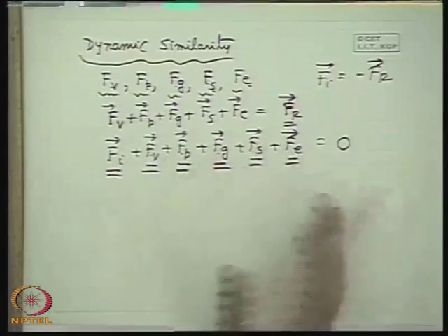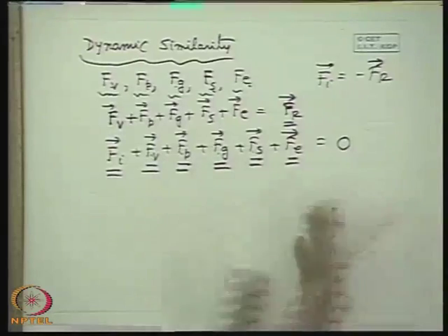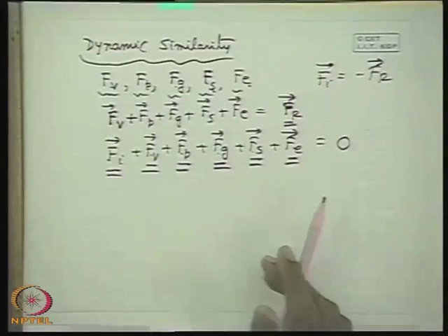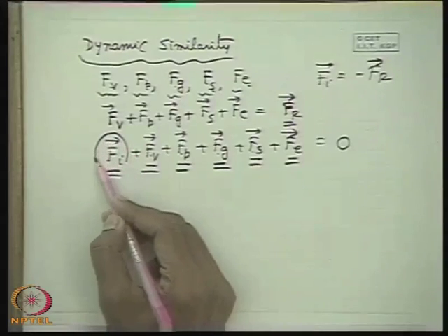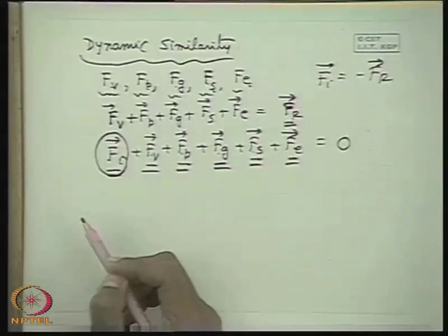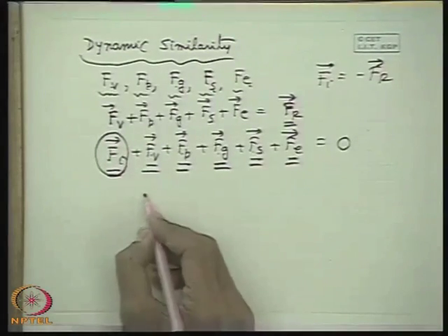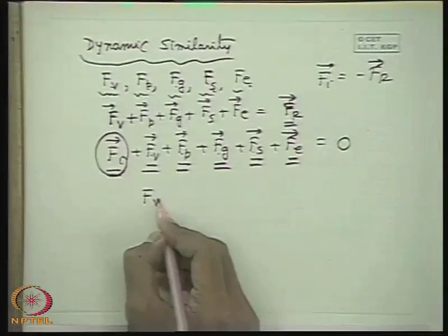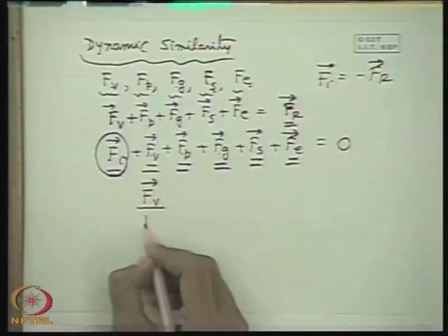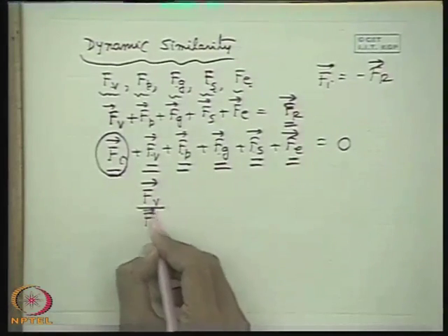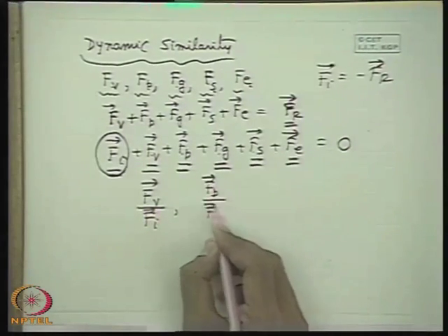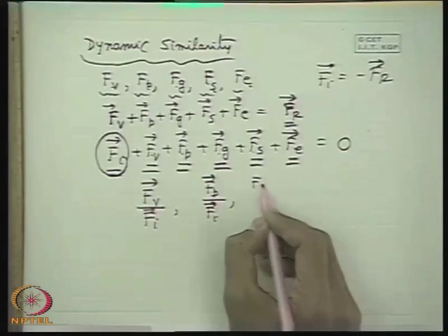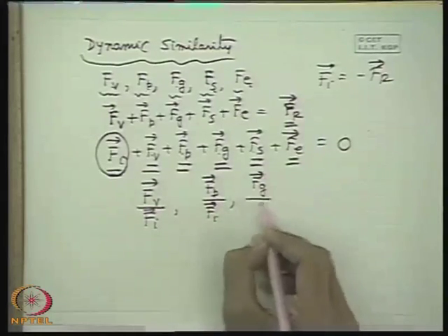So we have 5 ratios of the forces, or n number of combinations we can make, but the convention is that we always take inertia force as the reference force and develop the different ratios with respect to that. That means the ratio of viscous force to inertia force. Similarly, the ratio of pressure force to inertia force. Similarly, the ratio of gravity force to inertia force.